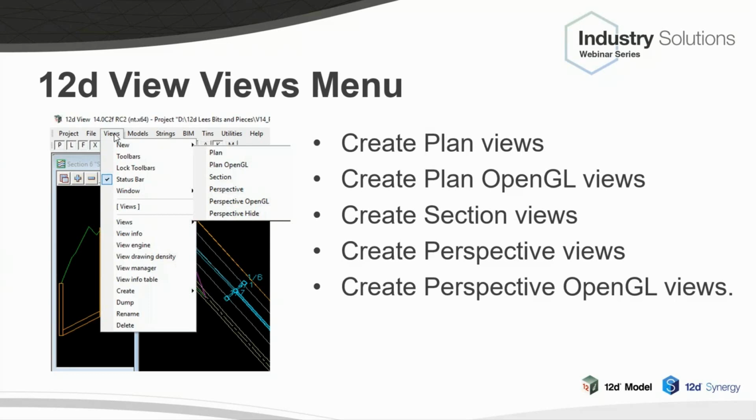And you don't want to give it a stupid value. I mean, what's the use of giving it 0 or something else because someone then must misinterpret it? And a lot of people use -999. And we had a customer in South Africa, of course, well, so that's not very good because we have mines that are deeper than a kilometre. And so the idea of a null Z value is very, very important. And by having the different view types, we can do it properly.